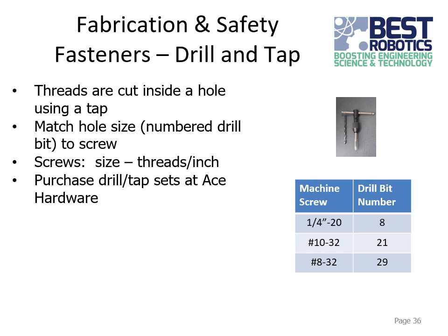What tapping a hole means is basically you're taking a hole and using this tap, which will actually cut threads into the hole, so that when you're done, you can screw a screw into it. You don't necessarily need a nut on the other side or anything like that, because the screw will fit perfectly where it has to screw into it.